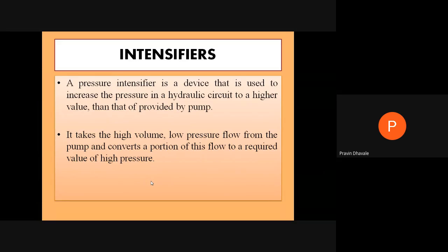Are you getting the intensifier? Simply, we have said that an intensifier is a device used to increase the pressure of hydraulic fluid, which is not possible to increase by using the pump. Means the pump has a certain limitation up to which it will increase the pressure. But whenever it is required to have fluid pressure more than the pressure produced by the pump, at that time we use the intensifier.